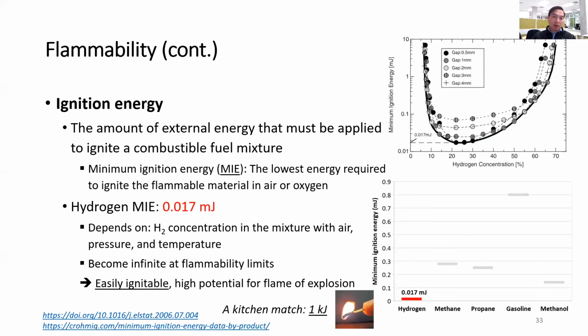All right, so we're talking about hydrogen fuel mixture, the oxidizer, and the composition between hydrogen and air mixture. And the next important thing in the fire triangle is ignition energy. This is the amount of external energy that must be applied to ignite a combustible fuel